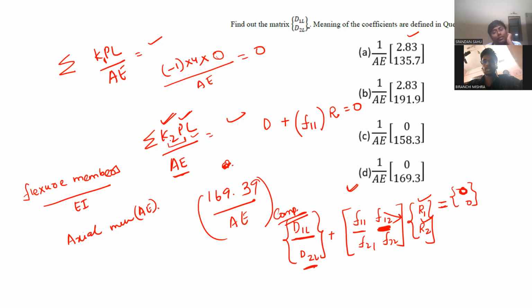Okay. You got it right? Stiffness, suppose K. This is F by delta. So force required to cause 1 unit displacement is called stiffness. So F equal to K delta means delta will be 1. Now, when displacement will be 1, at that time, the amount of force you are putting, that force equivalent will be called the stiffness of that system.